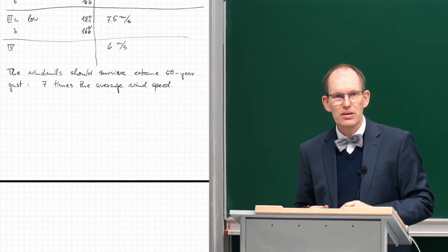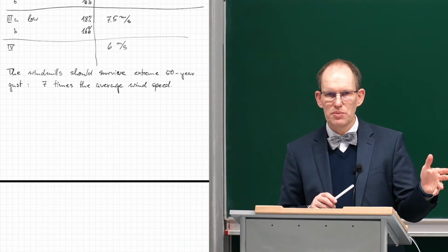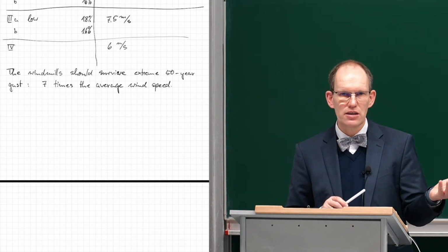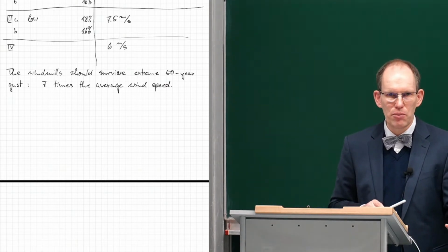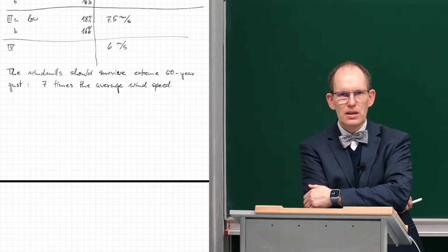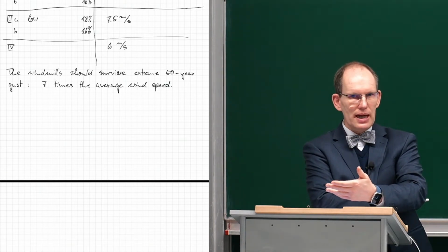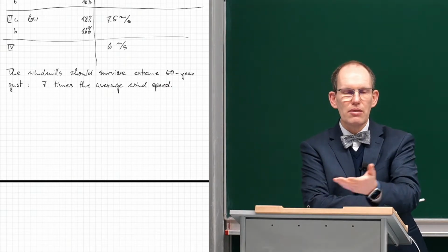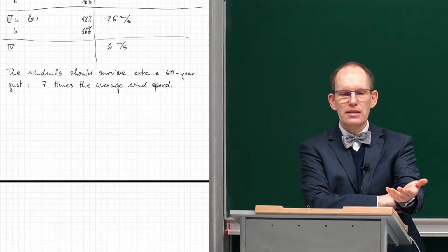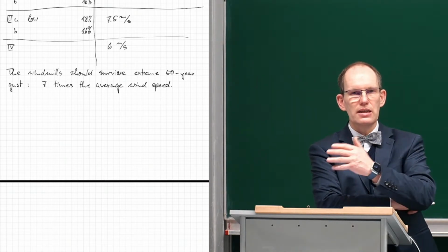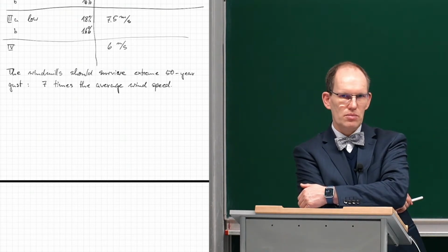Okay, let's come to the capacity factor. In German, this corresponds approximately to Volllaststunden. Yeah, so if you have a 10 megawatt windmill and it would run at its capacity at 10 megawatts throughout the year, then it would have 8,760 times 10 megawatt hours produced.